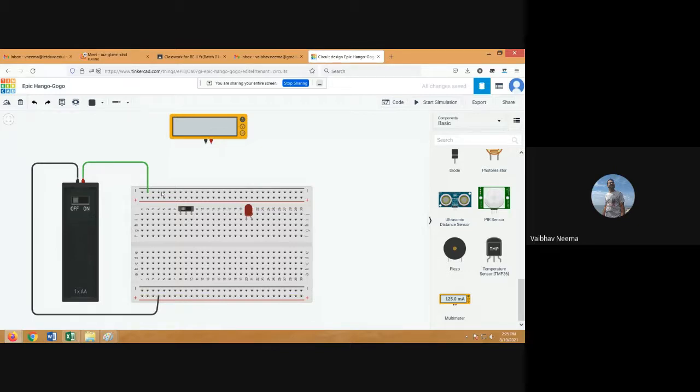Is that clear? You can see that if I select any of these connection nodes, they show the green color. Green means they are shorted, which means they have the same potential. So you can use either connection. They have the same potential of 1.5 volts, and this potential is grounded. So this is a ground terminal, a complete ground for your circuit, and this is the supply rail for your circuit. These are known as rail-to-rail connections. This is known as the power supply rail, and this connection is known as the ground rail. So we'll first make these two connections.